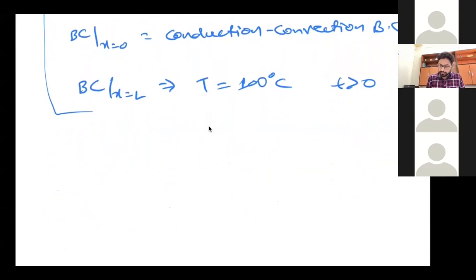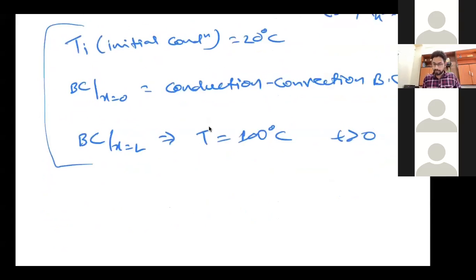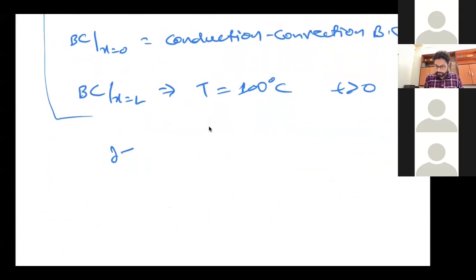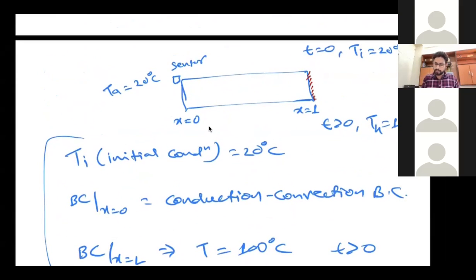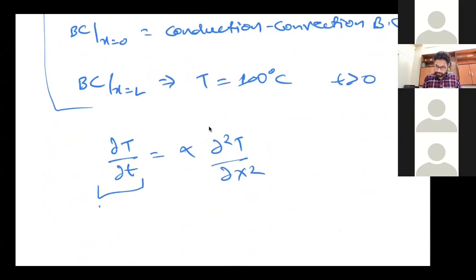The equation we saw before, as I said, is a function of time. It is changing with time, and that is why we need to consider the equation dT/dt equal to alpha d squared T/dx squared. Why are we just considering one term? Because we are modeling it as a uniform flow, assuming heat transfer happens in one direction, not all three. It is also changing with time, so this is the unsteady term, and this is the spatial term.